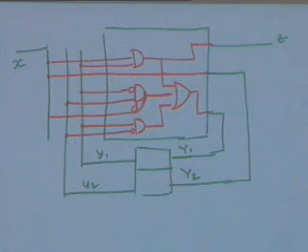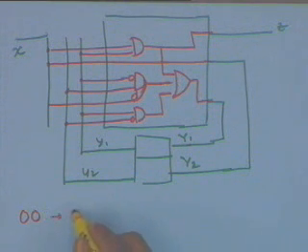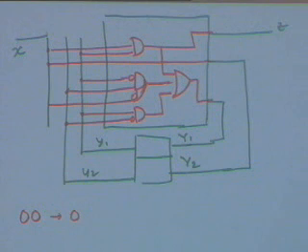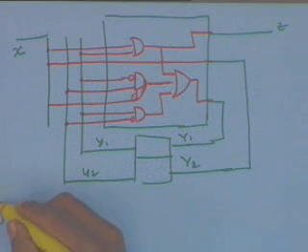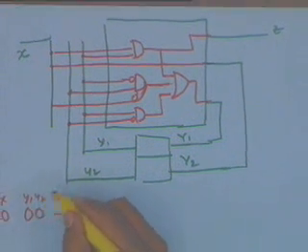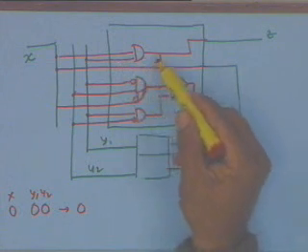And this circuit, we will spend some time and study this circuit very closely. I said I had this notional delay D, which I have made 0 for a moment. I don't put any delays, I just try to use the gate delays. But now if I look at it, what happens in this circuit? What I need to do is, when the input is 0, 0, output has to be 0, and I am in an equilibrium state, and remember the equilibrium was defined as excitation being same as the secondary variables. So if I have 0, 0 as x is 0 and your y1, y2 are 0, 0, when x is 0, your z of course output is 0, and this output is also 0.